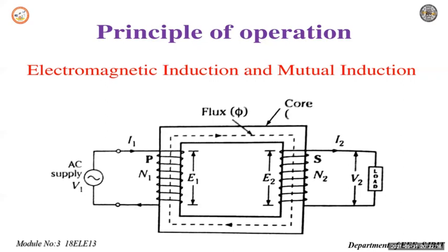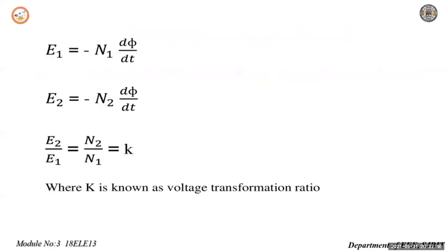This may cause the burning of windings due to extra heat generated and may cause permanent damage to the transformer. There can also be saturation of the core due to which the transformer draws a very large current from the supply when connected to DC. Thus, DC supply should not be connected to the transformer.